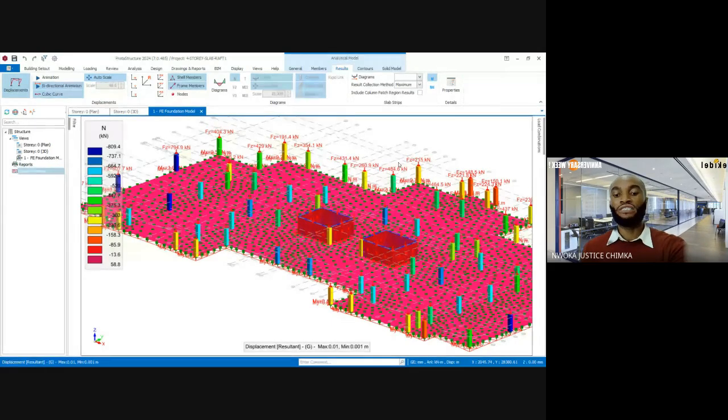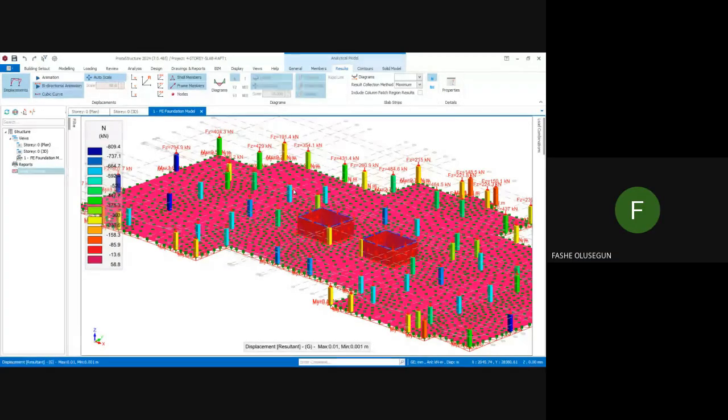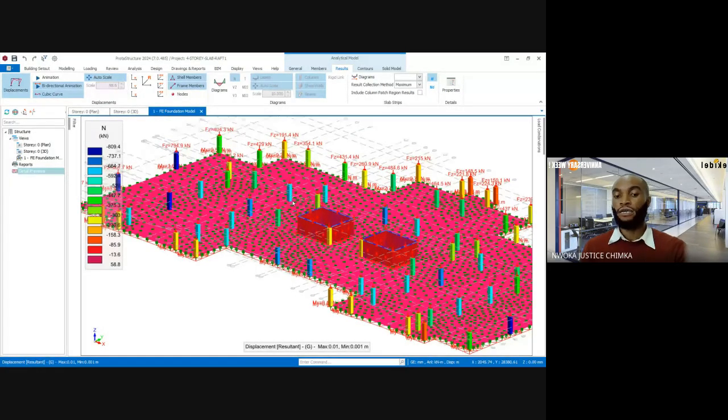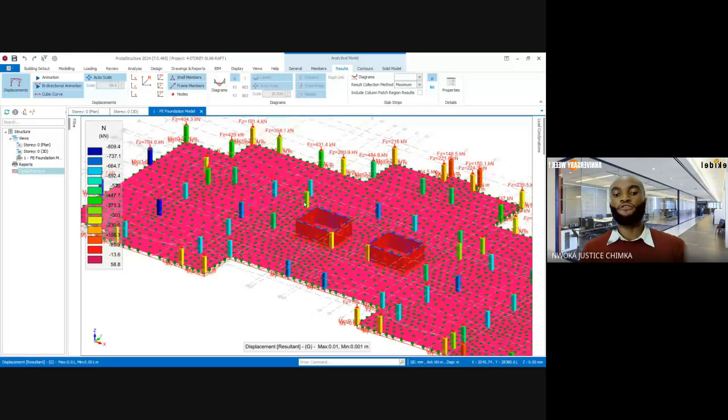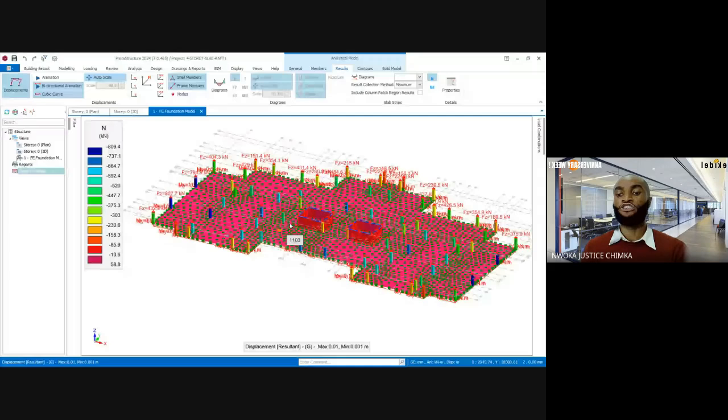Even if I'm doing flat slab, I still use this same principle. Even if I use that flat slab FE strip, I still make sure I check this and use this principle too. Exactly, cross check, because most times software can be giving you wrong results, because what you give the software is what the software will give you back. So this is what I trust more, by checking, using the area of steel to check what I am to get. So this is the method I use more.